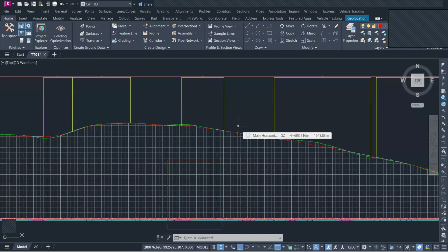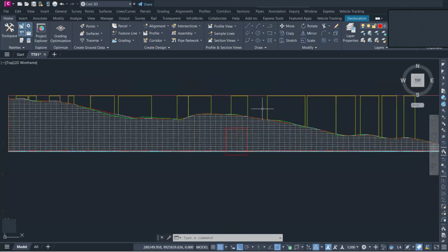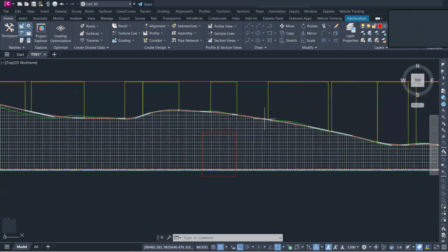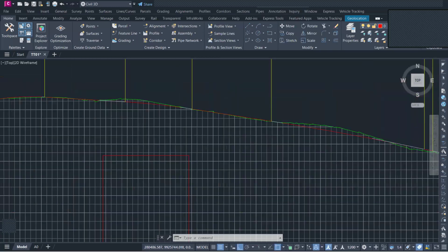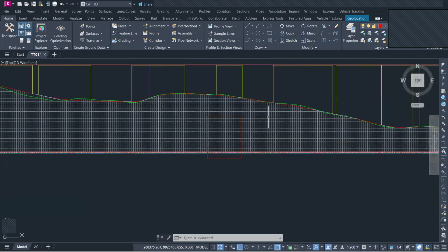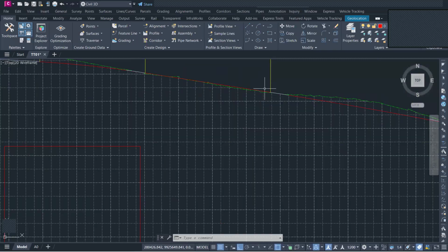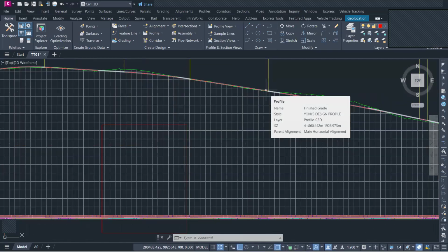The climate of the area matters. If it's a rainforest area, it means you will have a lot of discharge. Your hydrological analysis is also going to give you information on the amount of discharge we expect in that area. So, for example, this area receives a lot of rainfall, so you can have a reliever culvert. You can position a reliever culvert here. The culverts positioned on crest curves are mostly called reliever culverts.